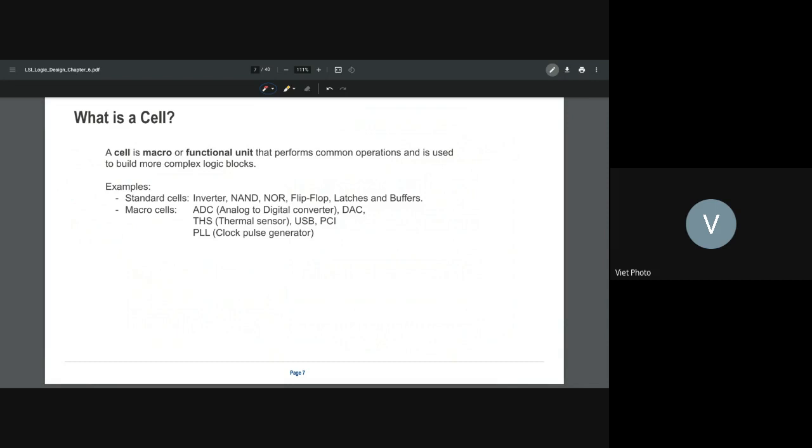So the standard cells like inverter, NAND, NOR, and so on, right? Then you have a standard cell. Standard cell means a very simple building block, which is inverter, NAND, NOR, flop, latch, and buffer. That's the minimum. However, along the way they also put in more complicated, complex cells like AND-OR-inverter, but it's still a standard cell. We can have that in this list.